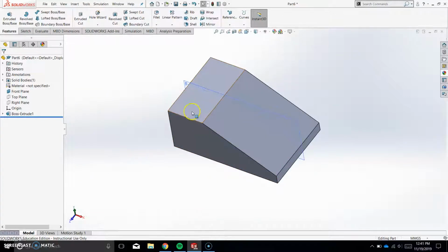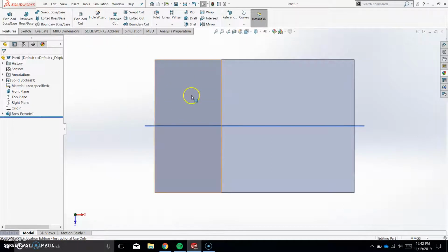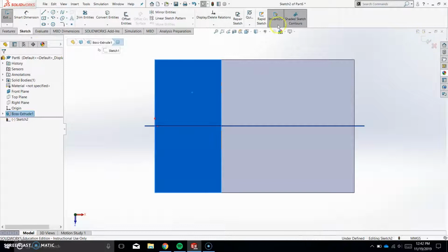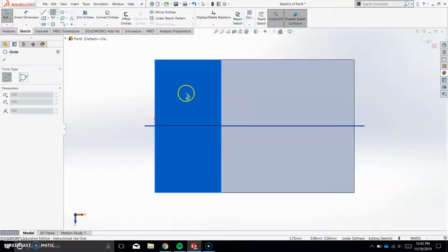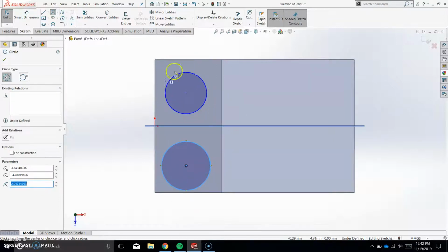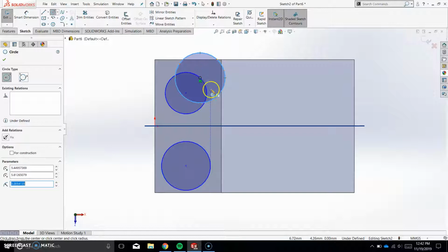All right, we're going to go ahead and sketch on this plane. So we're going to go on normal 2. Okay, click on the plane, click on sketch. You're in sketch mode. Click on the circle tool, make 2 circles. With the tool, like I said, the tool only lets you make circles. It doesn't let you edit, so it only creates more circles. You can hit undo here.